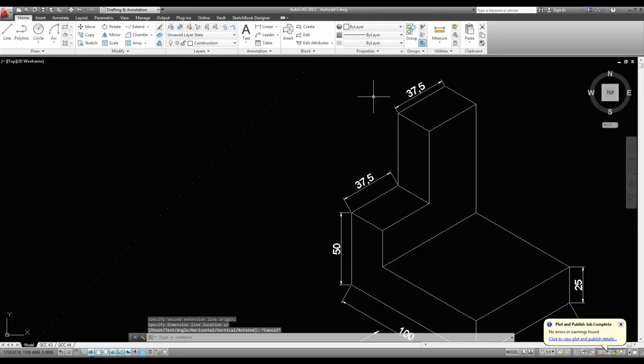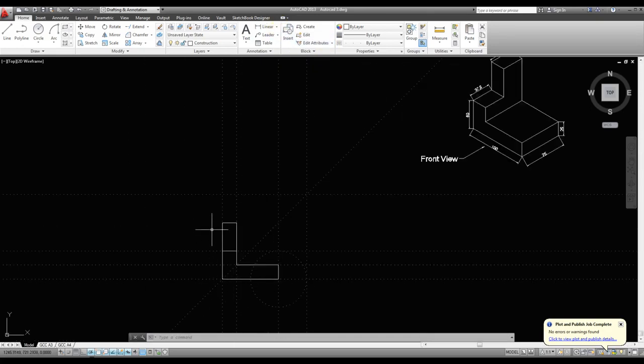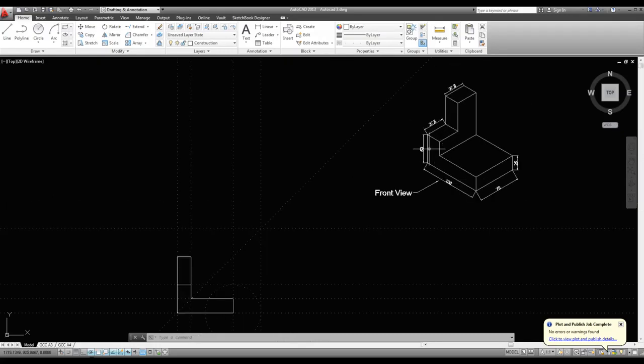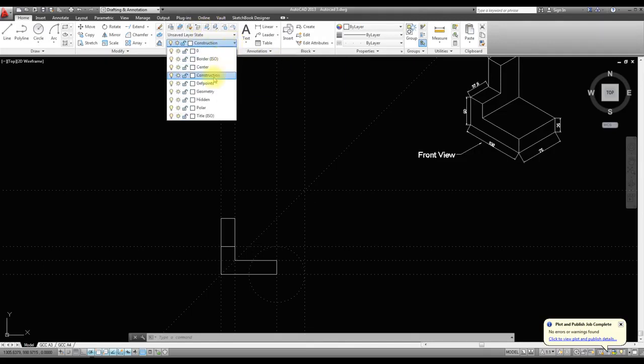But if I pick this dimension here and that there, what do I need to do here? That's not a true dimension. I know that's 100 anyway. So that height there is 100 as well. That's the thing with dimensioning isometric views. The actual dimensions are shortened, so you don't get the right measurement, whereas I know this one is 50. And I know it's 100 high.